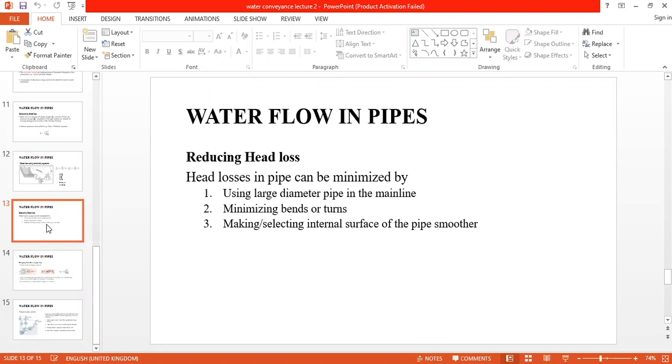When you're designing a system, maybe put the main pipe in the middle so that the branches which go to different sections of the farm are minimized, rather than putting it on the far end of your field, which means you have to put a lot of corners for the water to reach your destination. As you are designing, make sure that you minimize the bends on the pipe.